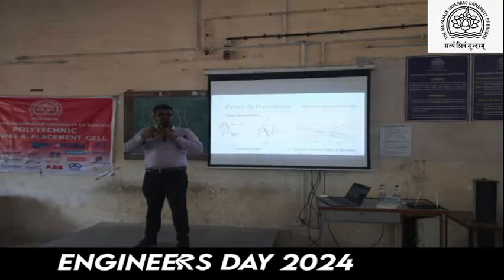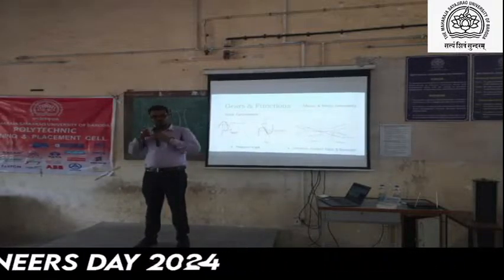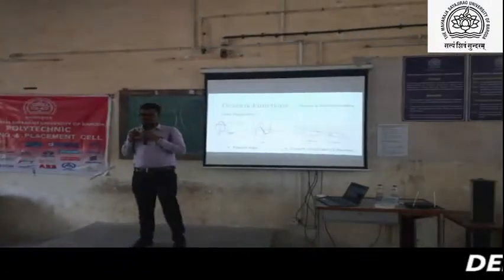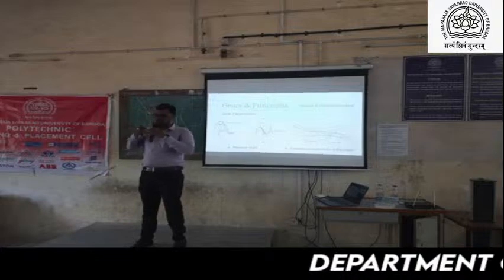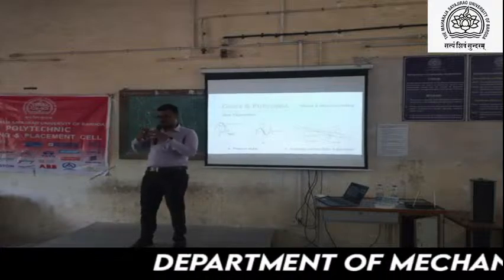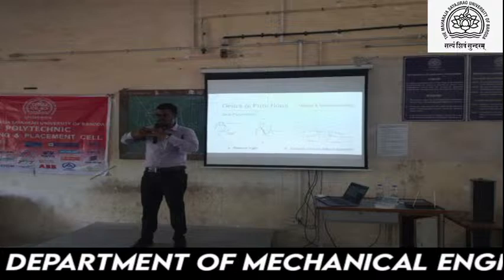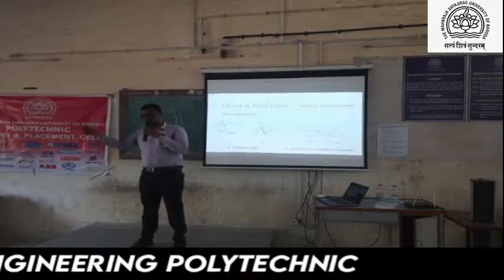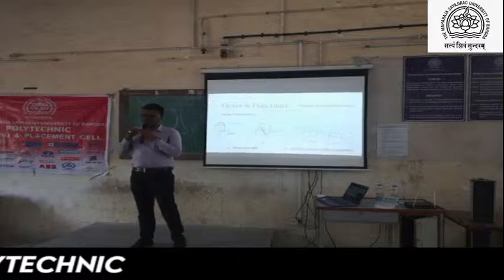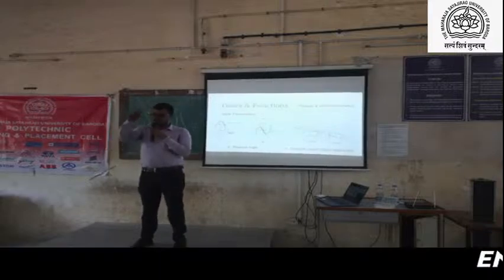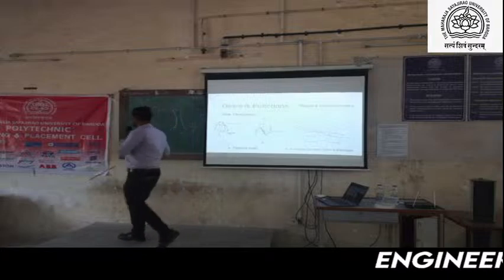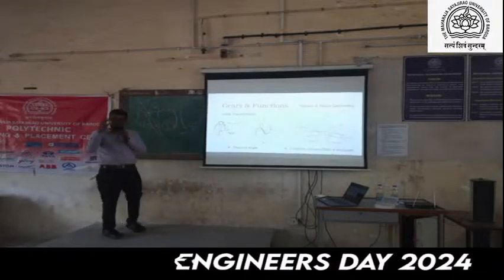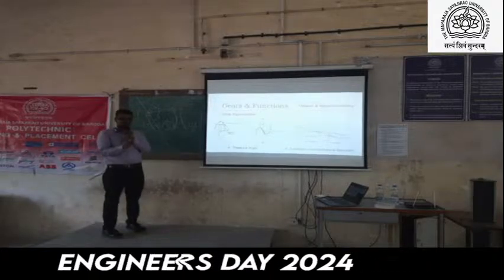One will be in full contact, one will be in partially engaging condition, and the other will be in partially removing condition. The same thing, compare that with helical gears. The contact ratio will be a little bit higher. Generally, in round figures, 3 teeth will be in contact for helical gears.